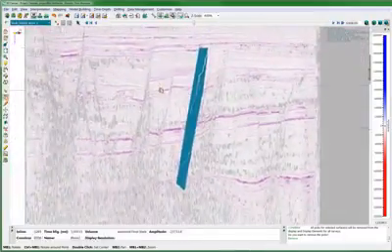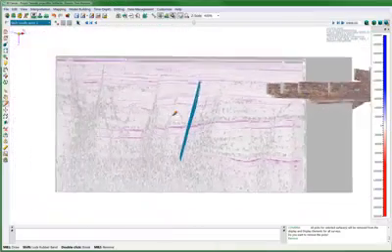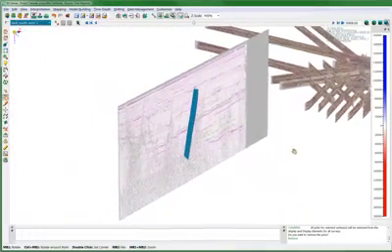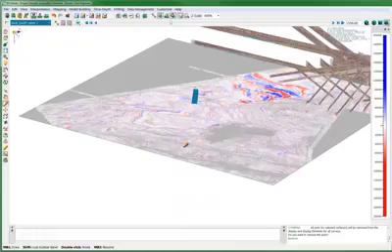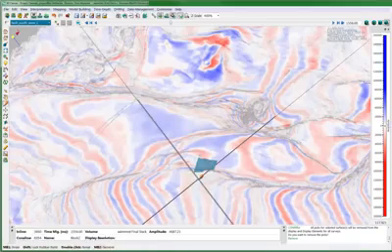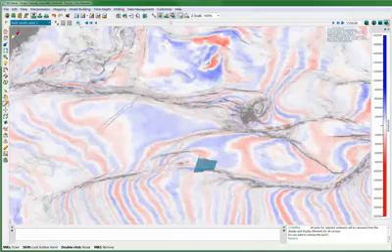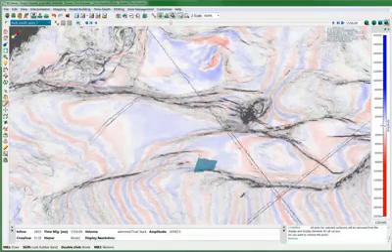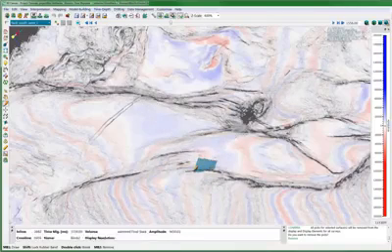All those fault sticks are manually editable, and we can continue the fault picking using amplitude and coherency by manually picking fault sticks on these slices. By pressing 9 on the keyboard, we are going to switch from crossline view to Z-slice. We can now zoom in and get closer to the fault to continue our picking in time slice. By pressing escape, I get my picking tool back, and I'm going to increase the weight of coherency on the time slice. We now see the fault better, and we can continue picking using the same fault on Z-slice.